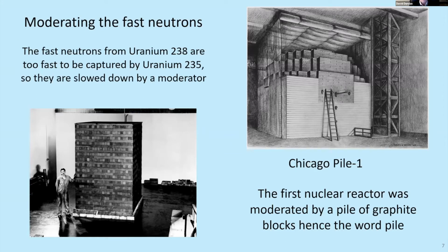And you can also change the amounts of capture of the fast neutrons by adding boron to the water. The more boron you have, the slower will be the reaction. In other words, the reactivity, the rate of fission of the uranium 235, because you want to be able to balance the rate of production of heat by the fission with the amount that you can absorb and transfer to heat steam to drive the turbines.